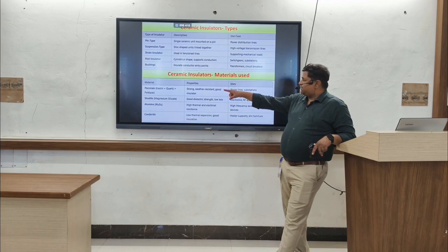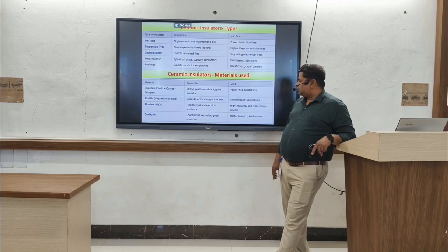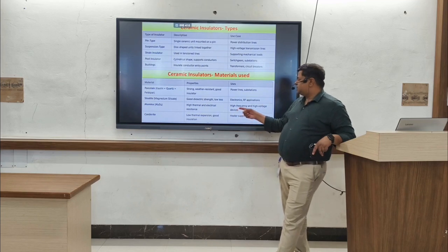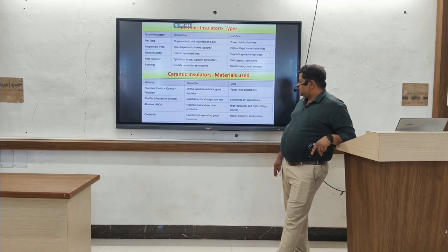If you say for porcelain, it is strong, weather resistant and a good insulator. Steatite has good dielectric strength and low losses. Alumina has high thermal and electrical resistance, and cordierite has low thermal expansion and good insulation. So their applications are also given.